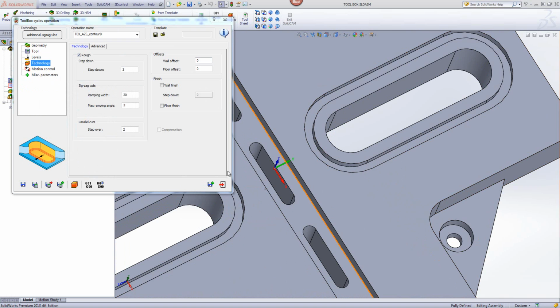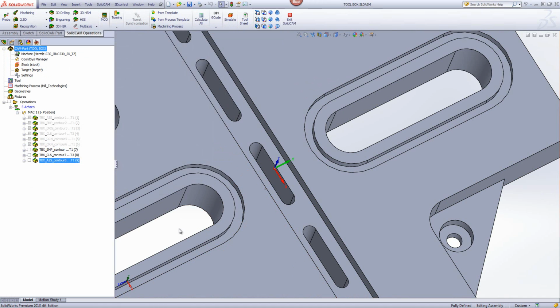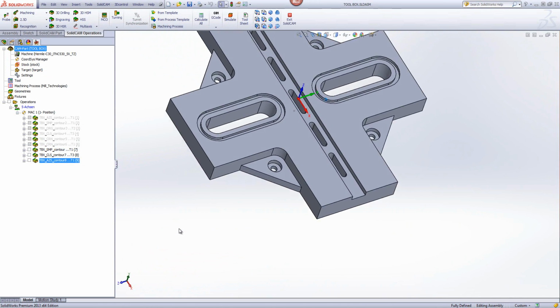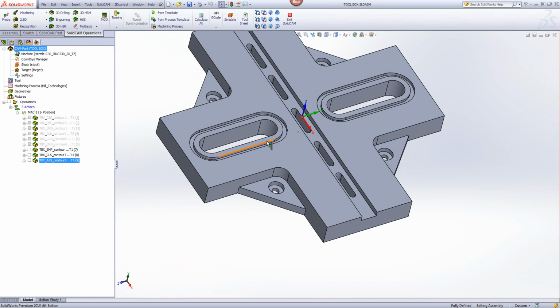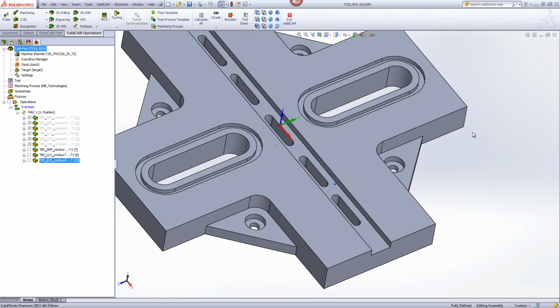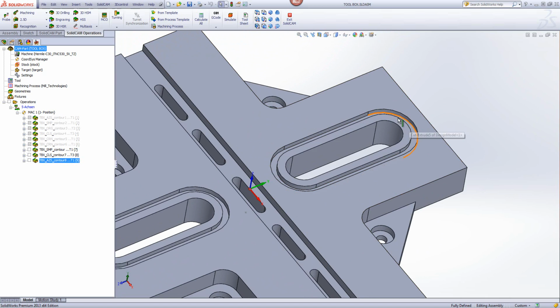Next, on the same part, we have these areas around here. This is very typical of having O-rings that you have to put on the parts itself. You'll have slots around pockets like this, whatever type of slot you may have, where you need to put an O-ring in. And the way I'd like you to work on the O-ring is very simple. I like to go down first in the middle and then clear off the side walls. And that's exactly what O-ring does.